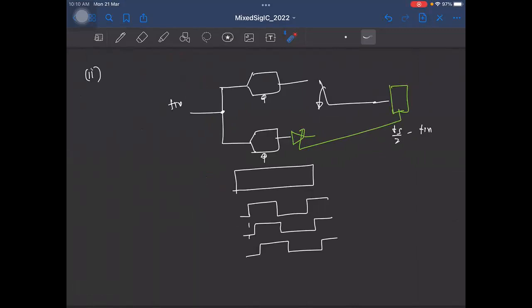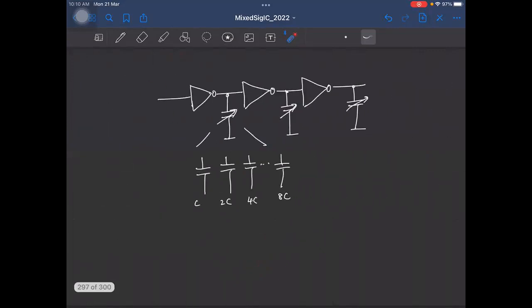And one way to correct for it is to have multiple phases of the clock, right? And you can select these multiple phases to feed to these other ADCs so as to correct for the timing offset. And this, of course, is one arrangement by which you can generate multiple phases or multiple delayed versions of the clock.